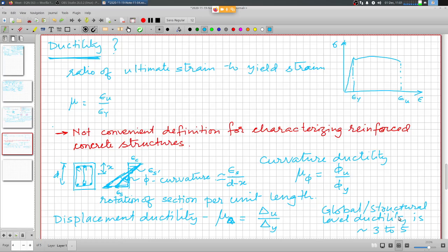Compared with ductility levels of 15, the response reduction factor, which typically accounts for energy dissipation by virtue of inelastic deformation, is only taken of the order of 3 to 5.